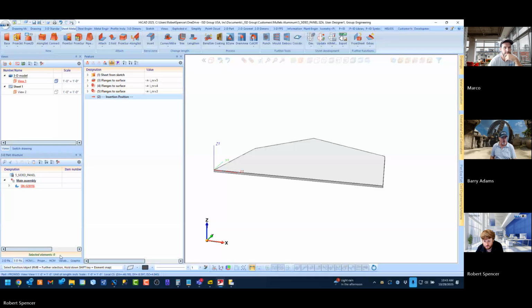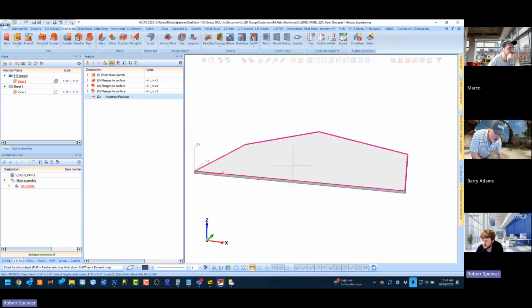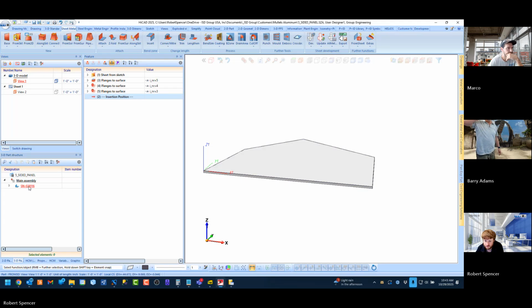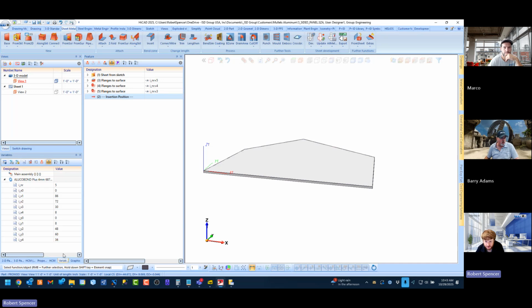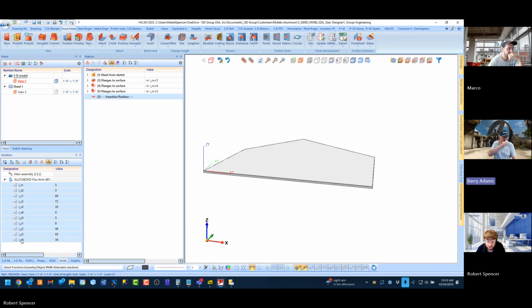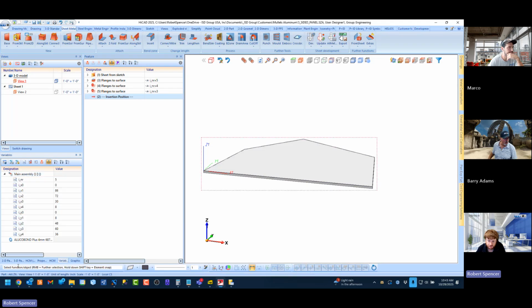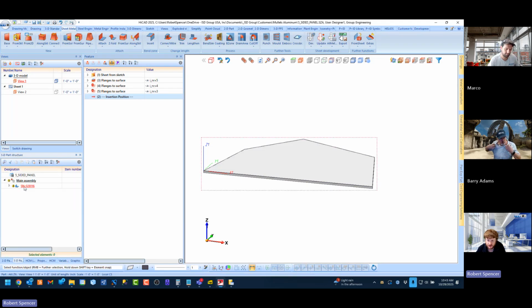Okay. So I know we only have this part, but typically you're going to want all your variables to be up here at the assembly level, because you're probably not going to have just sheet metal or ACM here.